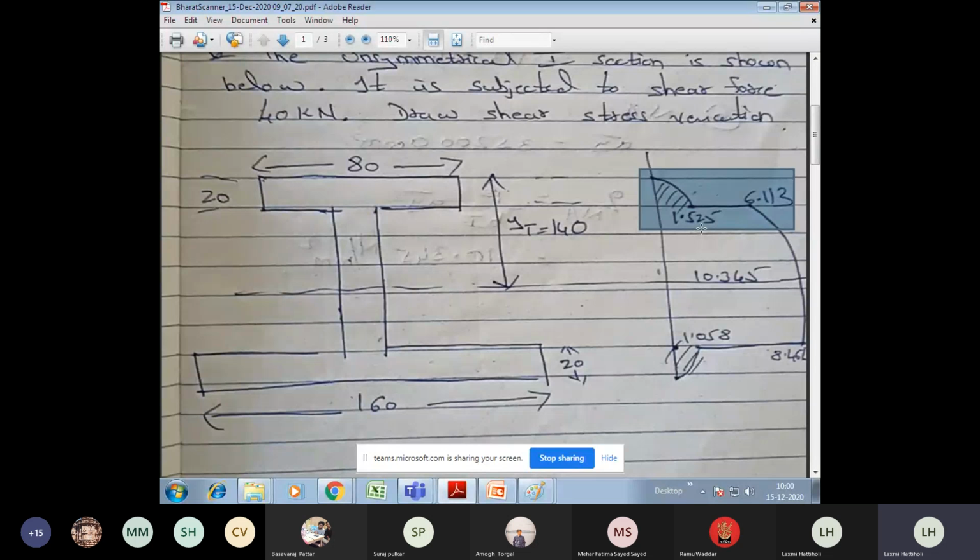That's why this is called a critical point: abruptly the stress varies because of the junction. You can see the cross-sectional area is reduced immediately at the web. Because of this, the junction should be taken care of if you are a designer.